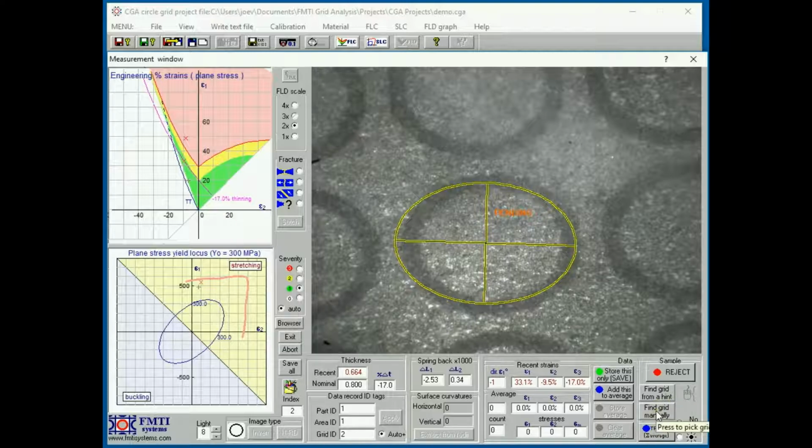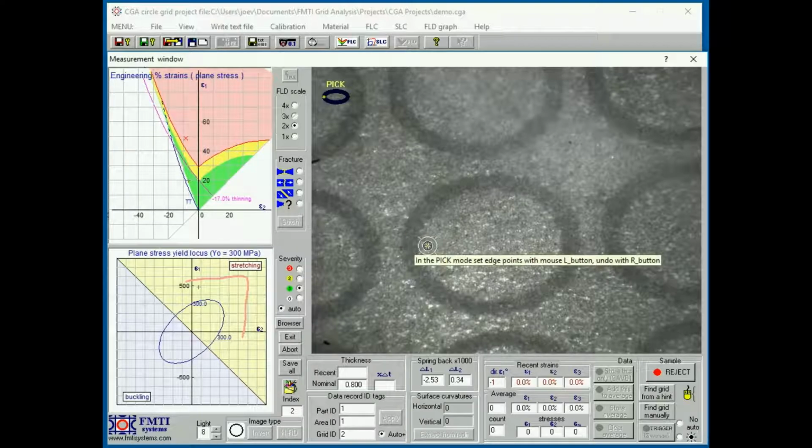right here. In manual mode, you just click that, point the center of the cursor to the middle of the line, start at one point, go to the opposite. There is an indicator here telling you what to do next, and this is good alignment, so we'll say OK to that. Then you specify the other axes. If you make a mistake and click there instead, before hitting OK, just hit the left button and reposition it where it should be, so you don't have to redo it.